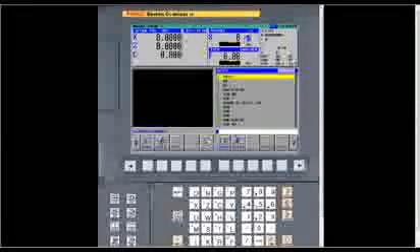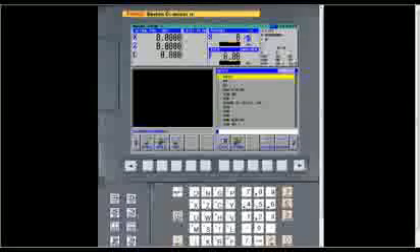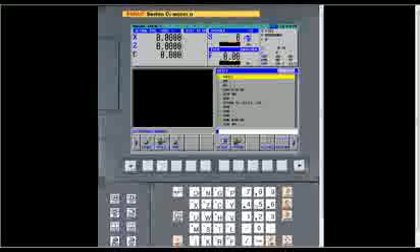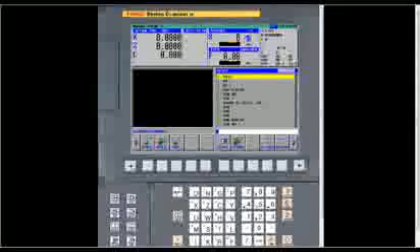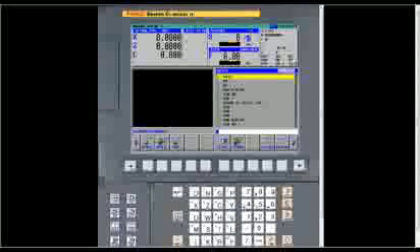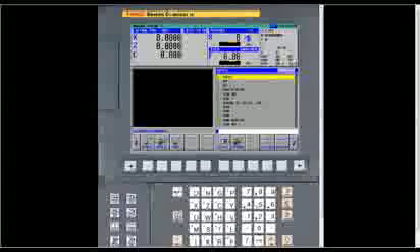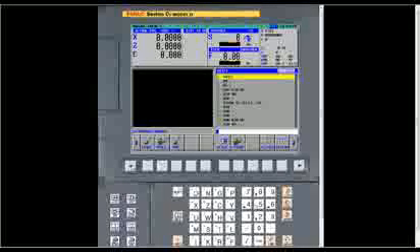Oh, yeah, that's no problem. I mean, when you're doing a turning cycle with a hollow cylinder, say you're boring out the inside of it, the last move that you would make would actually go down to the smallest size of that hollow cylinder, and then the control would know that that was where the stock would be removed. So it's very simple to do that. It's just based on the geometry that you described for that hollow cylinder within the turning cycle.